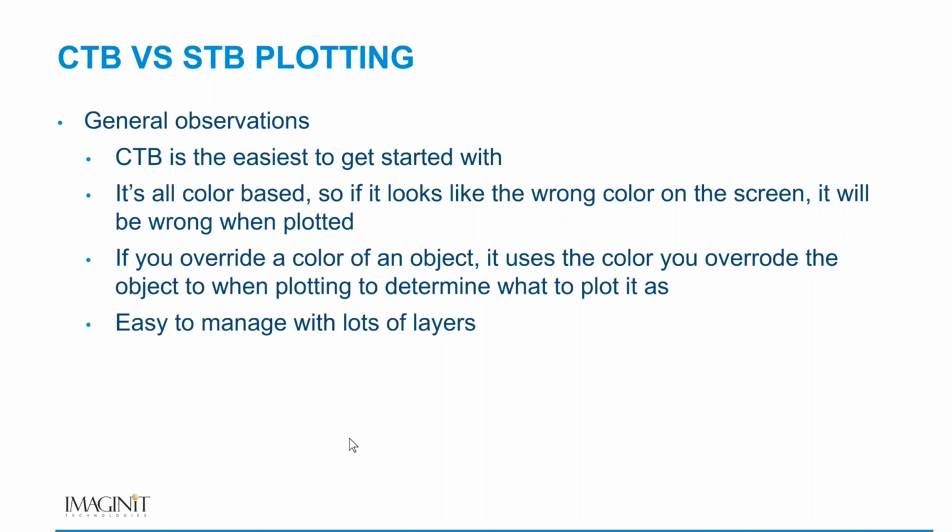CTB is not necessarily the default. It's being driven by your template. So whatever template you start with is what is driving whether or not it's CTB or STB. And I'll give you an example of that.